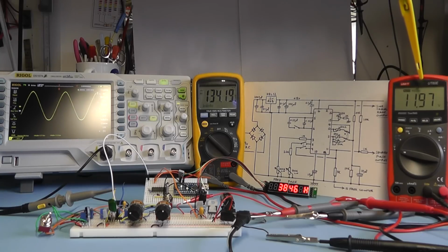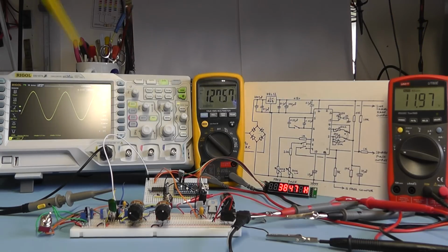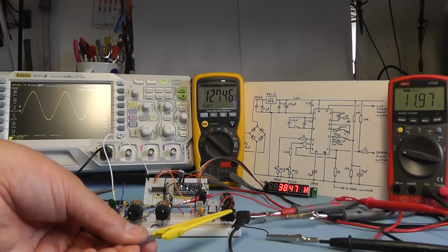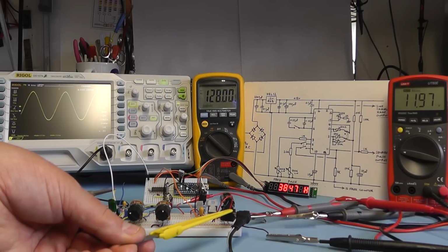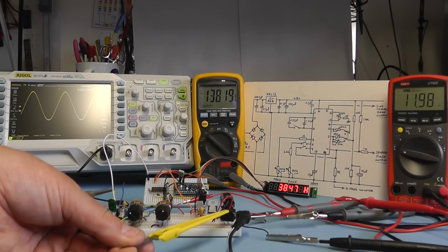And you can now see that our 12 volt supply is more or less spot on. It's 11.97, so that's back to more or less normal now, and I think that's the reason why our function generator is working correctly. So I think the key there is to use an AC power supply to feed this that is capable of supplying 12 volts and a little bit more current than what we had previously, so probably around about 1 amp. You may even get away with 500 milliamps.